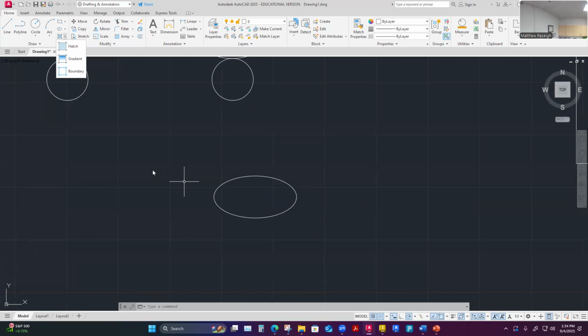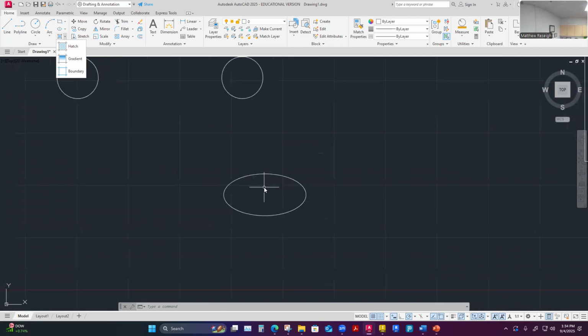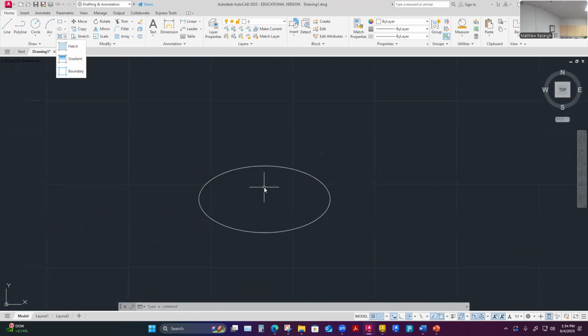It's just that in my drawings, I can actually do invisible cuts and expose the insides of things, just to show people that might be building stuff what the inside will look like. And sometimes, so the viewer of my prints knows what's going on, I apply a hatching to that, so it catches your eye that I'm looking at a material that's been sectioned so I can see inside of it. It doesn't mean I'm going to build it like that, but it allows me to view the inside of something that I might be building.